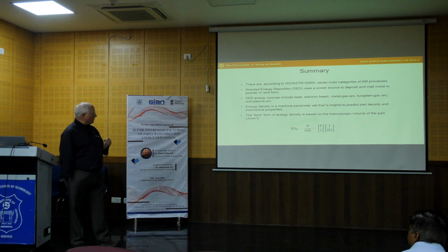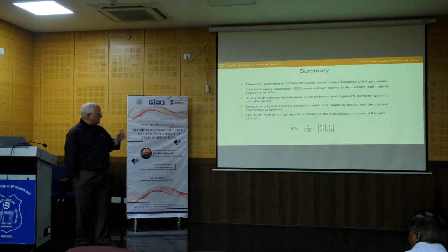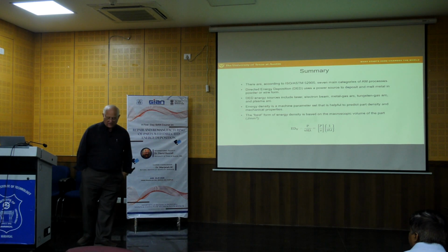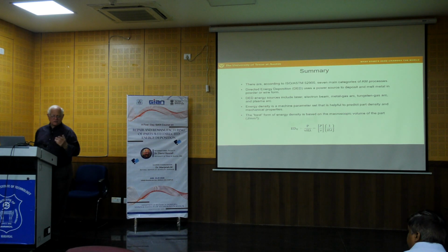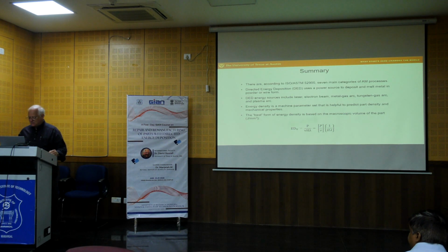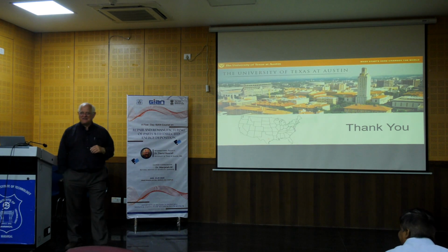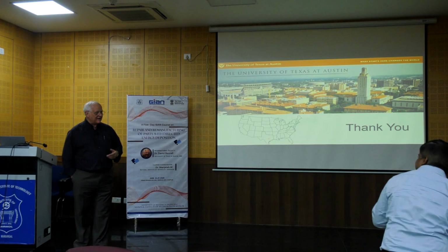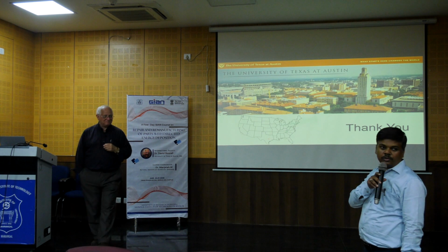And then finally, I think the best form, and indeed the most popular form of energy density, is P over V H lambda, where H is the scan spacing or the hatch spacing, and lambda is the layer thickness of the beam. So with that, it gets me to the end. So again, I show my end slide again. I don't think I have to explain it this time. But I guess we have maybe an opportunity for questions. Thank you, sir. Any queries from the audience?